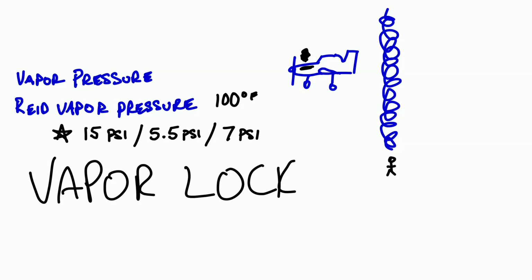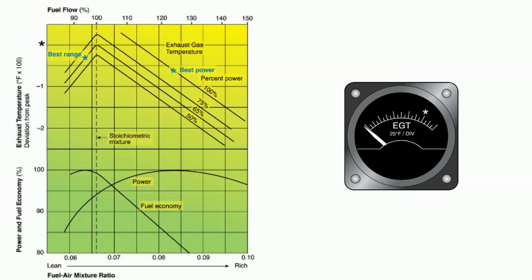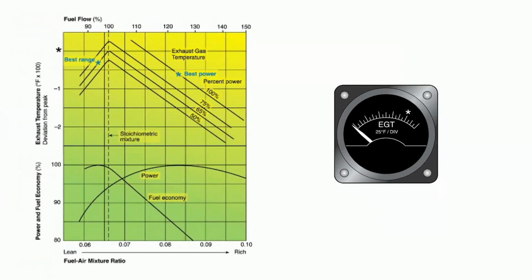Now, there's a couple systems that we'll talk about a bit later on about how these fuel meters actually work, but what I want to focus on is how all of this relates to fuel mixture. Now, aircraft engines have a distinct differentiation from automotive engines in the fact that we have the option to control our fuel mixtures, which is actually kind of cool because we have the ability to lean or enrich the mixture manually depending on the altitude that the engine is flying at and what the requirements are.